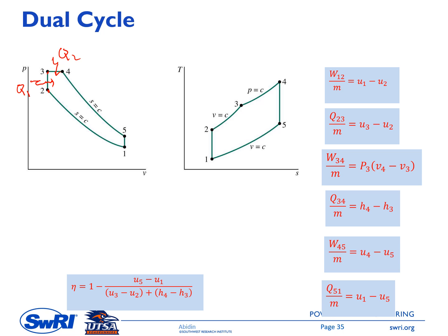In the TS diagram, see here, you have point 3 and then point 4. The first one is at constant volume, the second one is at constant pressure. And then the work required to compress the mixture is W12, which is U1 minus U2. This one is negative, but if you want to get everything positive, you can reverse it. So W12 is U2 minus U1.